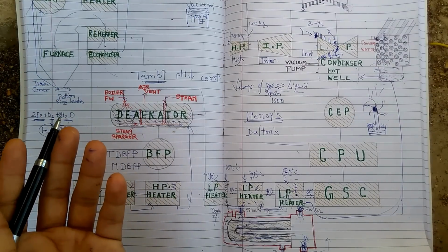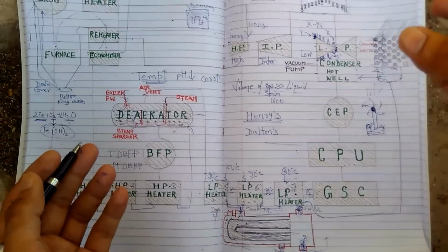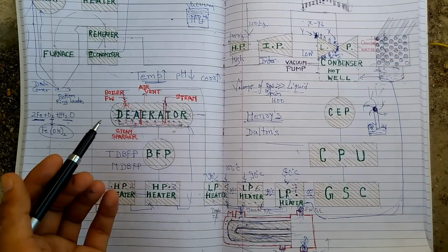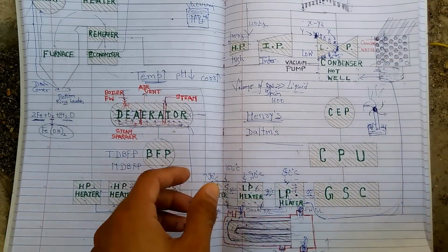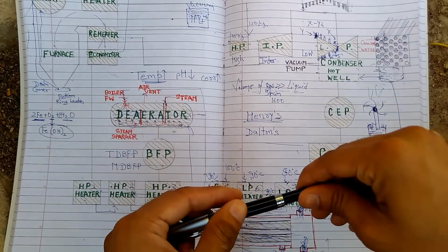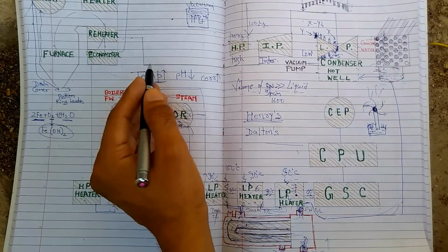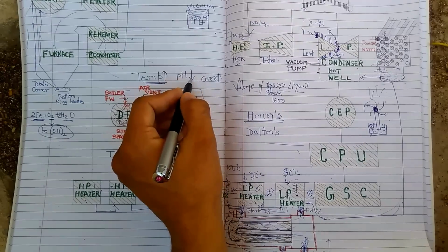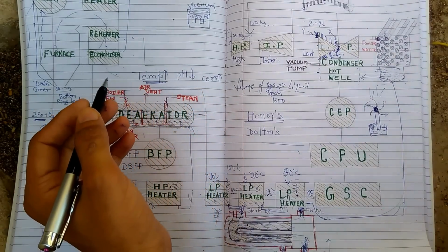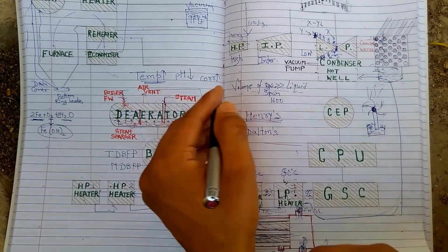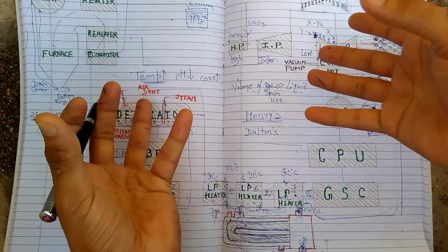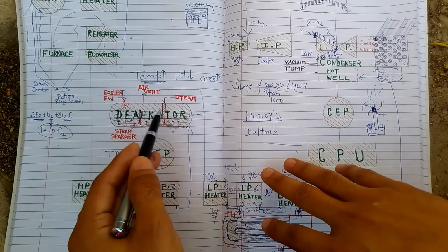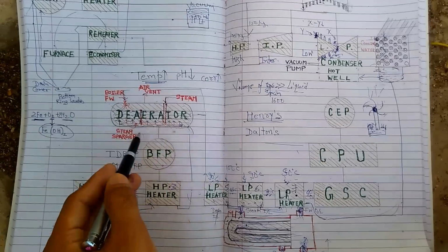If I do not remove carbon dioxide, by reacting with the metal it will create carbonic acids, and those are again corrosive. Okay, the corrosion in this system depends on three things: the temperature, pH value and oxygen content. If I increase the temperature of the system, my corrosion will be more aggressive. If I reduce the pH value, that is I go more on the acidic side, my corrosion will get more aggressive. If I increase the oxygen content, my corrosion will get more aggressive. Okay, so I have to remove that oxygen and carbon dioxide from this feed water.